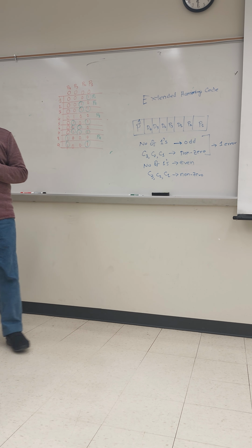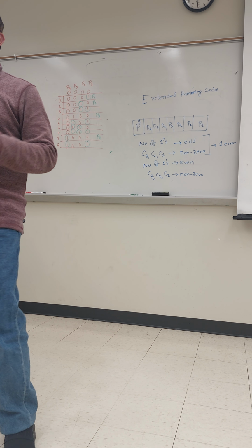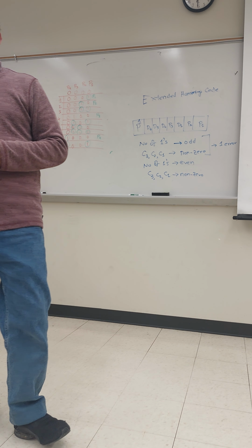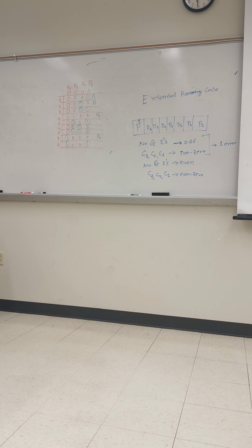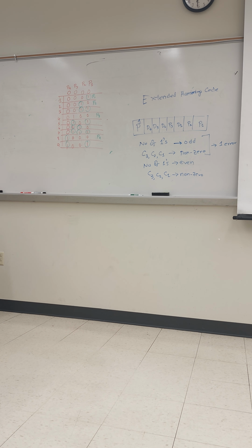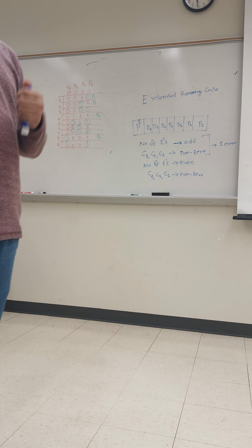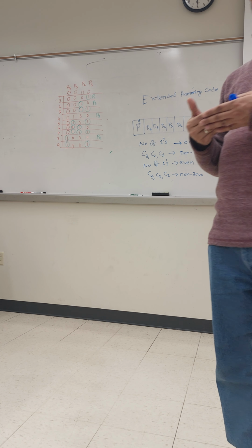Of course, if you want to find more error positions, we need to extend more bits, but it will cost us bandwidth. So this is also one of the major problems of digital communications. In analog communication, the major problem is noise, because in analog communication we use amplitude modulation, we send the amplitude signal, the varying signal. So noise is also an amplitude, and it easily interacts with our signals.